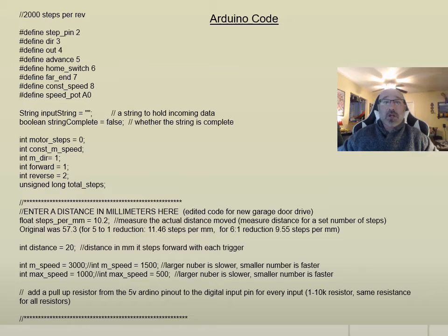What we've done here is we've started our Arduino code, and one of the main things we need to figure out is that we have this system on motors, and we need to translate the revolutions of the motors, the rotation and the speeds of the motors, to the actual speed and positioning of our antennas on our radar cart on that linear drive. We took a look and calibrated these out and found that it's 2,000 steps per revolution, and we want to know how many steps we need in order to get the resolution that we need for our data acquisition to acquire the images of the underground buried targets. So that was a big portion of it: calibrating and setting it up and translating from motor speed and position to physical cart position and speed.